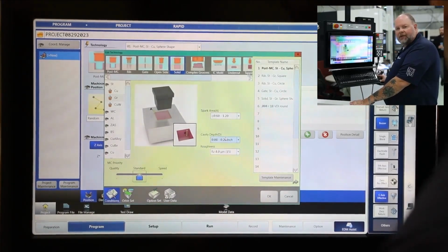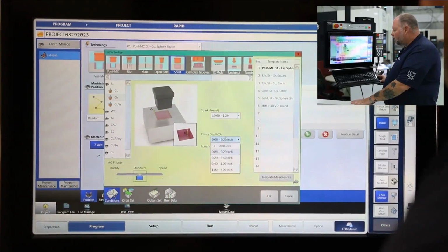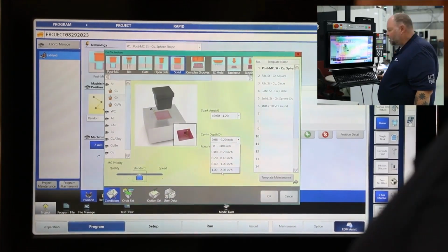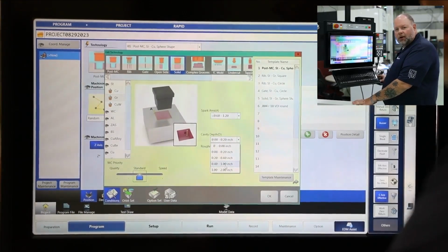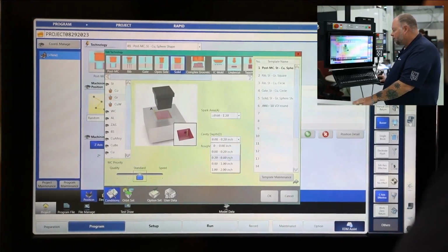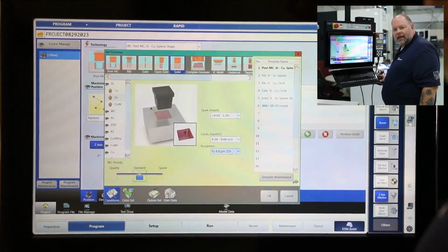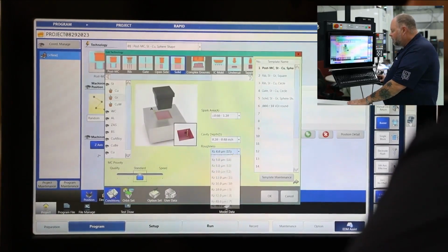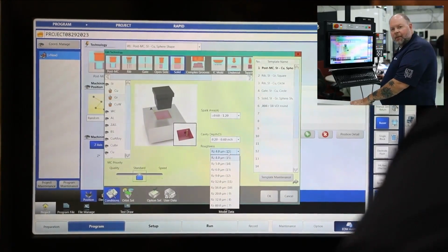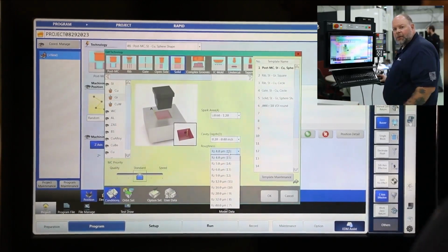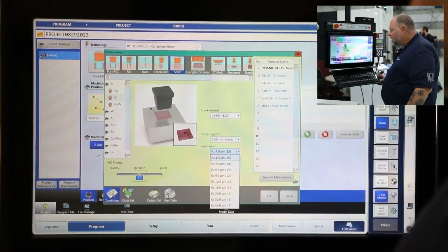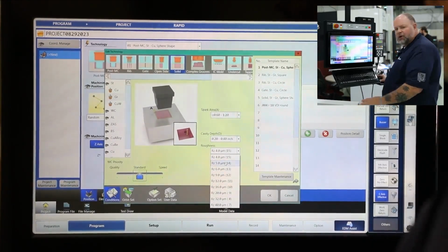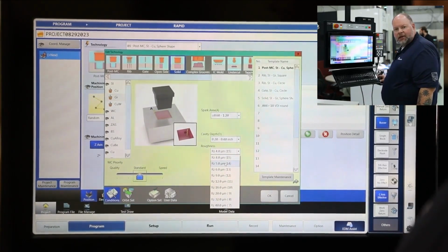Next, select the cavity depth, how deep that we're going to burn. Again, in ranges anywhere from 80 thou up to 2 inches deep. In this case, we're going to go 250 thou deep, or a 1/4 inch. And then lastly, I need to pick my surface finish, or on the machine, what we call roughness. Here we can have scales in micrometer RZ, micrometer RA, or VDI. In this case, I have the machine set up for micrometer RZ, and we're going to burn to a 5 micrometer RZ surface finish.